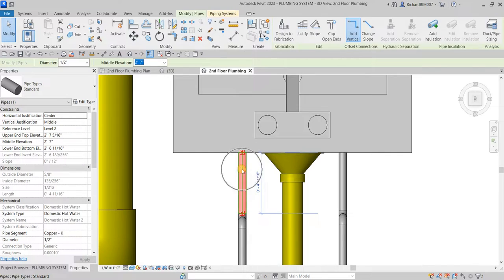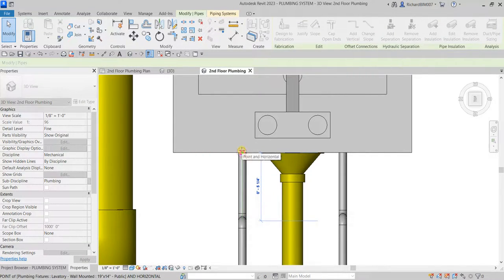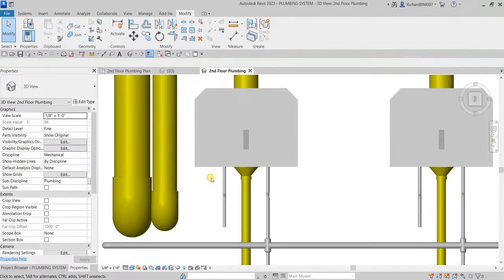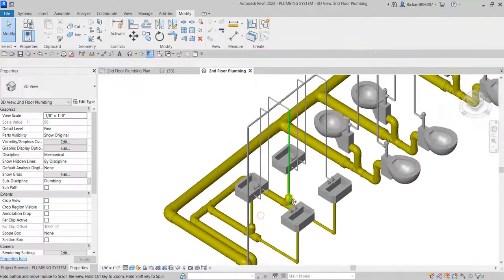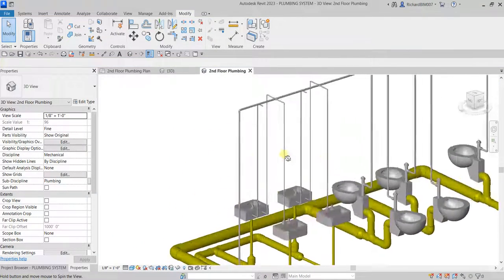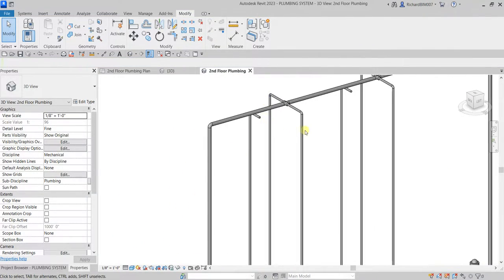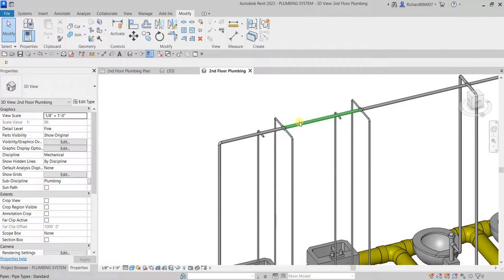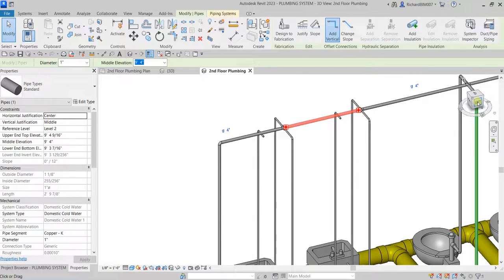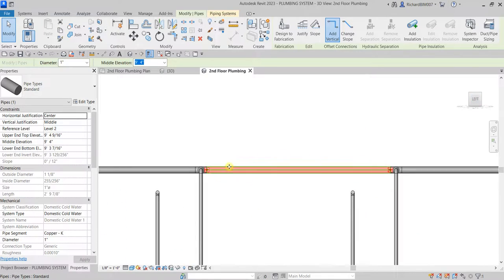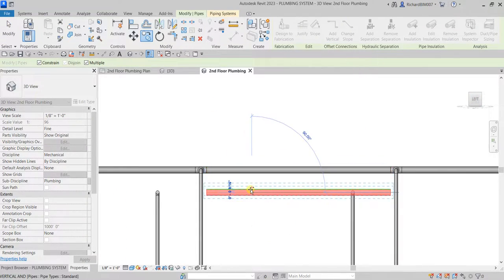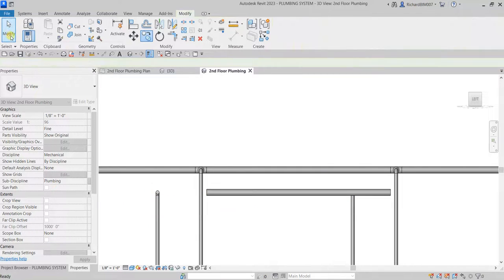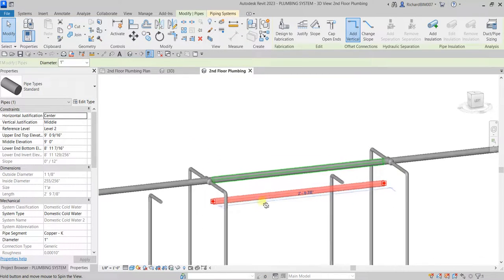Make sure this one is connected. So click that node. There you go, and then connect. We are connecting that here. Okay, and we need to have another pipe, right? So let's say I'm gonna select this one, and then I'm gonna copy that. Go to the left side, select this, copy, move down. There you go, modify. Now we need to change the type of this.